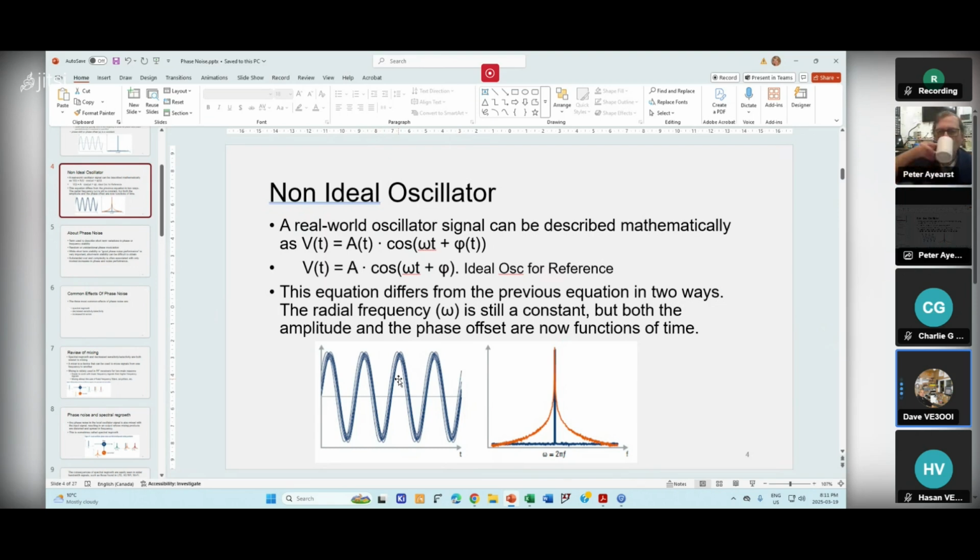Let's take a conventional frequency counter. Typically, you count a certain number and you multiply it, or you divide by n or something. There's some kind of divide or multiply that you're doing. If you've got a fraction and you're doing a divide, you lose that fraction. So if you've got 13.2, and you do a divide, you could lose that 0.2. Or if you multiply, that could add up to 1 hertz.